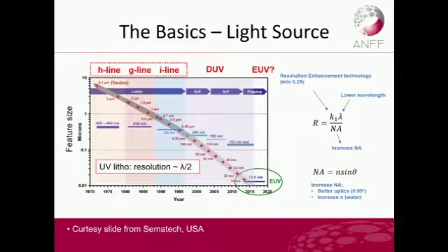It doesn't make any sense to you. But the way the industry is doing is that they would use what they have on hand and try to improve from it. And they have been doing this over and over again. So the resolution limit for 193 nanometer exposure actually kept at about 45 nanometer.